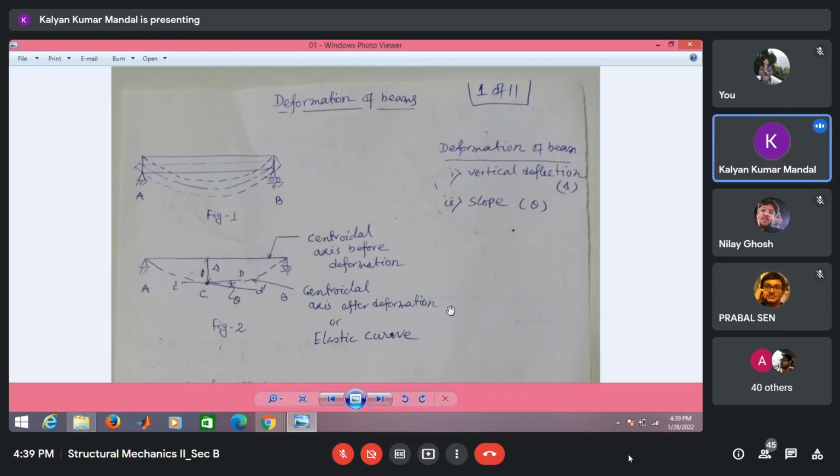Yes, just a minute. Let me explain. What is the primary stress? The primary stress means the stress due to the direct applied load. This is one part of the stress. The second part is if the structure deflects too much, or if the deflection of the structure crosses some limit, then there will be stress apart from the stress due to the direct force. This stress due to the excessive deformation is called the secondary stress. This is not for the direct loading. This is the indirect stress.